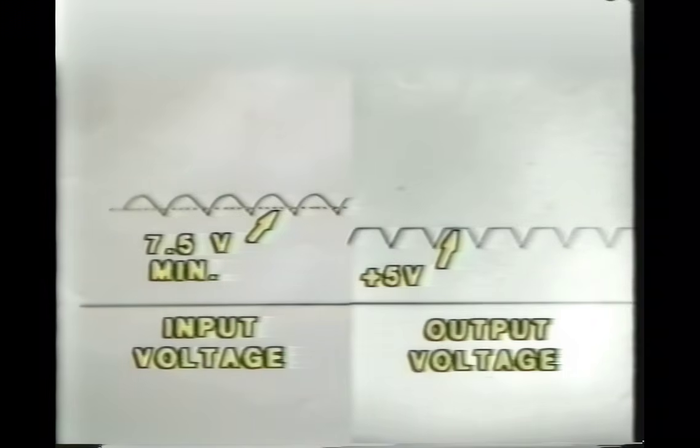There's a common problem that we see in video games that recurs quite often in power supplies, and this comes under the heading of diagnosing a bad filter capacitor. A lot of mechanics have quite a bit of trouble repairing power supplies when they have a bad filter capacitor. The reason being that you see all kinds of strange readings, and if you don't know what to expect, you really don't know how to interpret the readings that you make. So let's take a look at this power supply and see what happens when we have a bad filter capacitor. When a filter capacitor fails, it generally loses its ability to hold a sufficient charge.